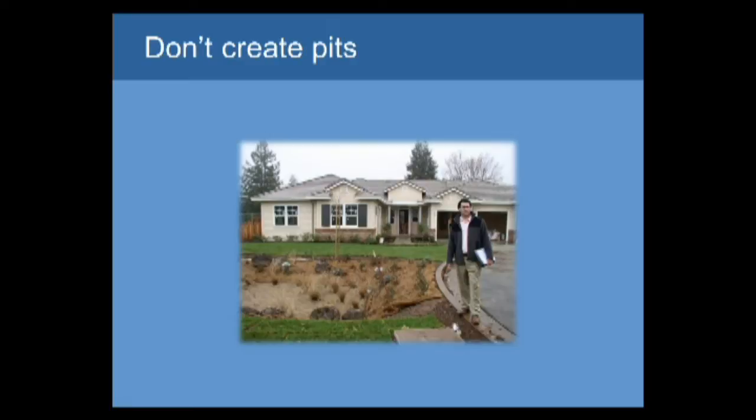And the reason Dan is so unhappy in this picture is because the potential buyer had just come and looked at that house and said, I'm not going to spend $1 million on a house with a pit in front of it. So he was on the bleeding edge of this. They did eventually re-engineer this. They tight-lined that downspout and used it to bring that drainage right out here and bubble it up to a level elevation which is just right at close to the street level, and rebuilt that facility, and he sold that house for what he had expected to sell it for.